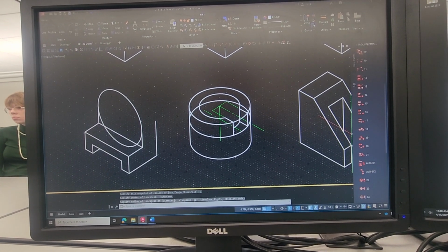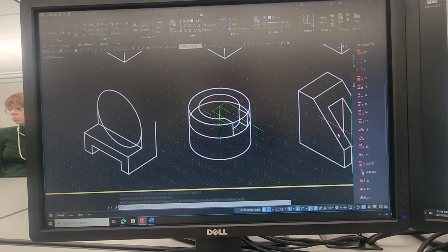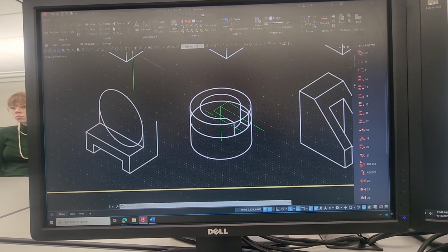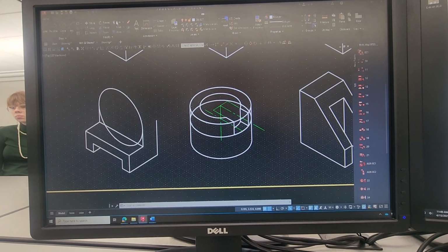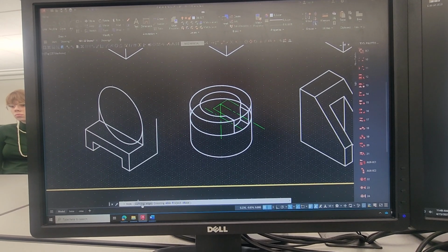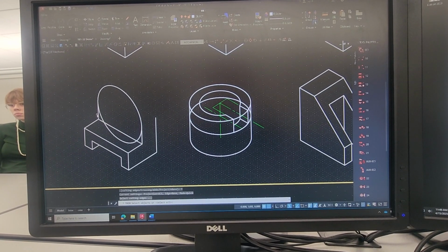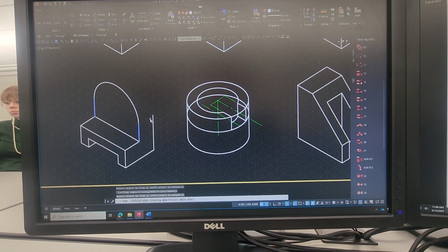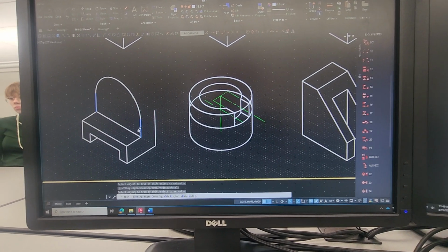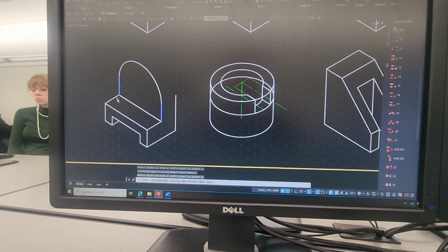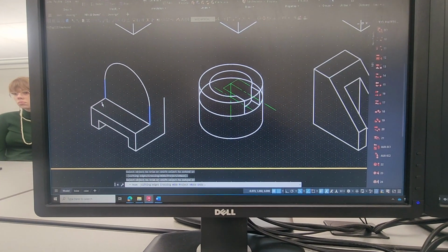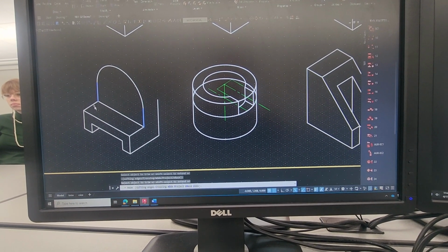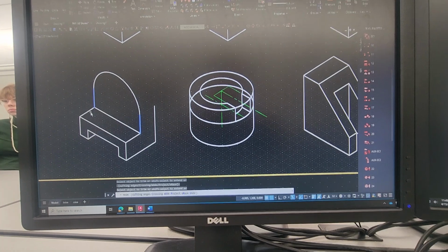Now in order to make this, you see I've got a pair of these back there. Absolutely fine. But what I want to do now is trim. So beware of this. When I go to trim, it's always best to choose cutting edges, choose that cutting edge and that cutting edge, and then click the line you want to go away. If not, you're going to be doing little points, pop, pop, pop, cut off by the grid. Does that make sense? It'll drive you insane. You're going to be clicking over and over to try to get what you want. So just pick the edges.